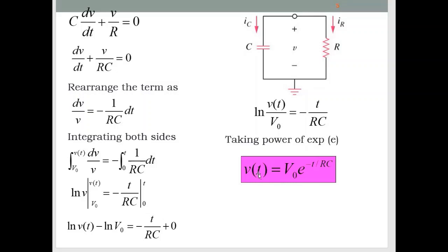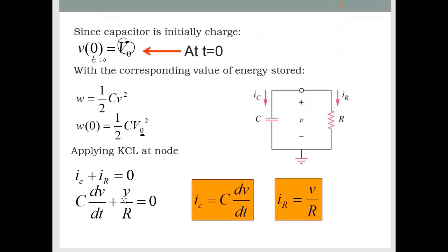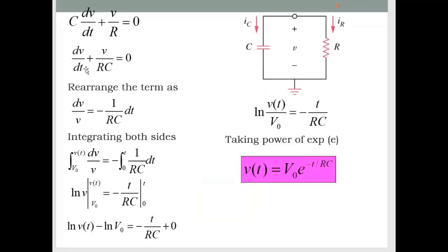Because to get this final V(t) from this equation, you need to rearrange the V here, and then to remove the differentiation terms, integrate the two parts here, and then you will get ln, and finally you will get this equation for RC circuits without the voltage source or current source: V(t) equals V0 e to the negative t over RC.